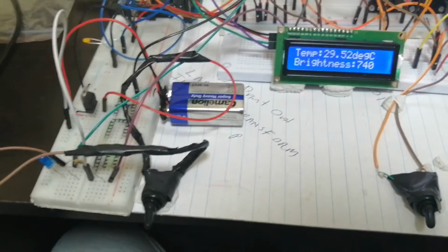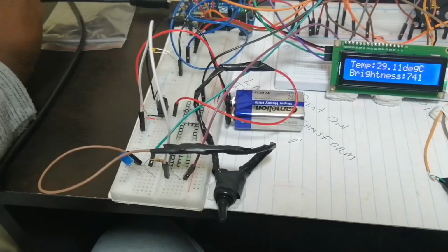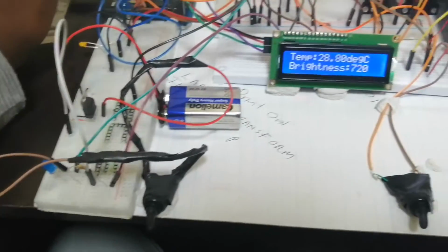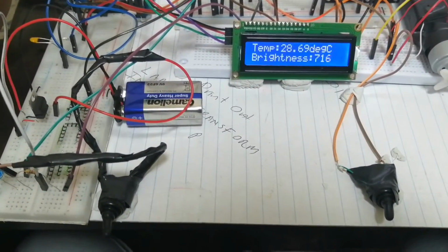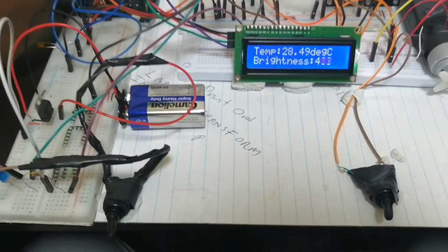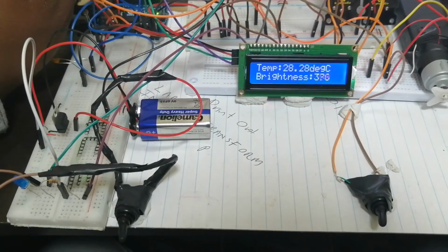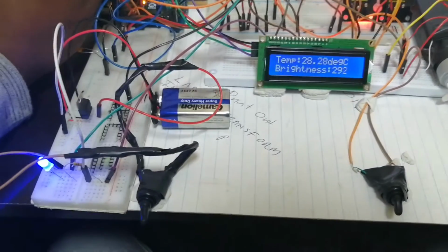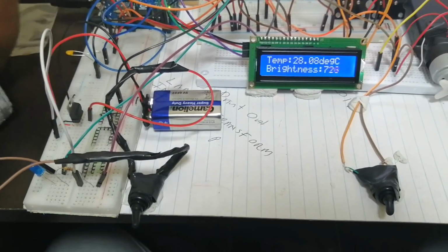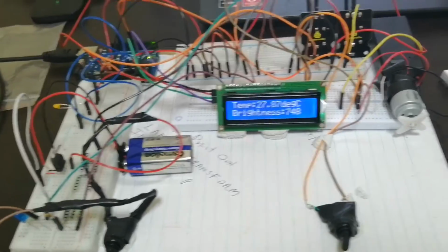Basically I'm just gonna cover the LDRs to demonstrate the darkness, so that the LEDs, which are the lights, should switch on. Okay, there we go. Looking at the brightness decreasing, as it decreases below 300, then it's gonna switch on the lights. Here we go, check. Then as it goes, when it's brighter than 300, then it's off. Yeah, basically that's it for the program.